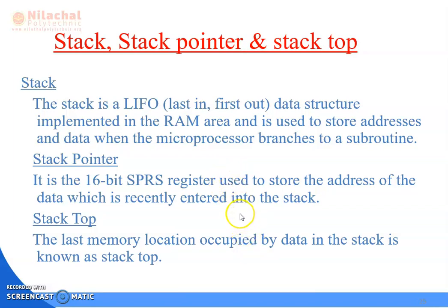It is the 16-bit special purpose register used to store the address of the data which is recently entered into the stack. Then what is stack top? The last memory location occupied by the data in the stack is known as stack top.